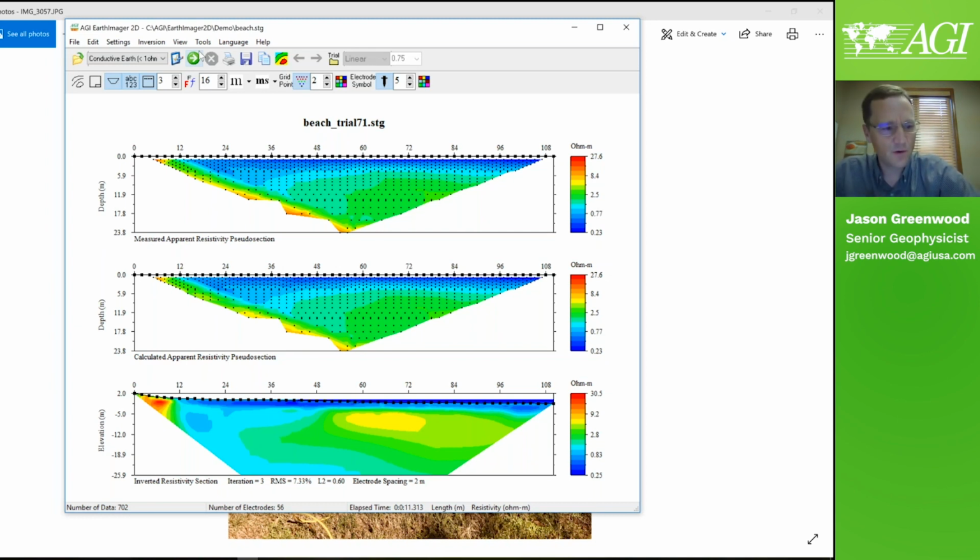Salt water, 2% salt water, is a good method, though it may drain quickly. You can add some powdered bentonite to it and make a bit of a slurry. The bentonite itself is conductive, and you wouldn't need the salt, but you certainly could have it as well. That bentonite can be messy, so there's a drawback there. If salt water doesn't do it, then go to bentonite.